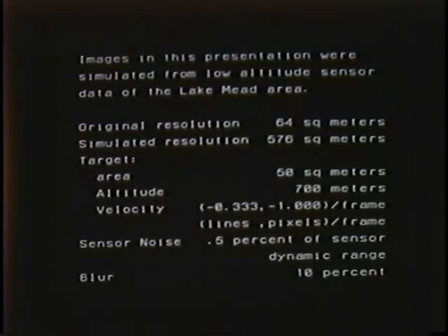A smear factor was even modeled in the simulation. Smear is analogous to the effect created when a photographer uses a slow shutter speed to take a picture of something moving very quickly. The object that is moving gets blurred or smeared in the photograph. Lastly, random Gaussian noise was added to model flaws in the sensor. If you look closely, you can see that the pixels in these images seem to be twinkling. In real images, this is caused by electronic instability in the sensor. The specifics of the simulations are shown on this chart.